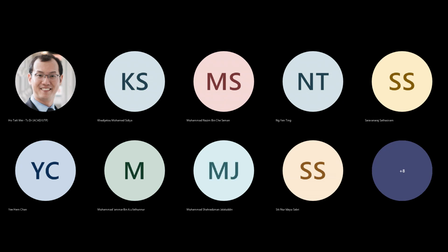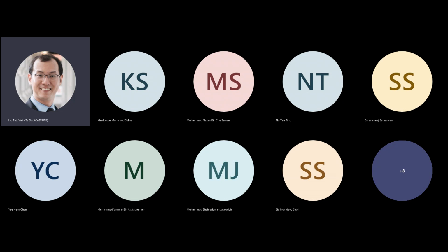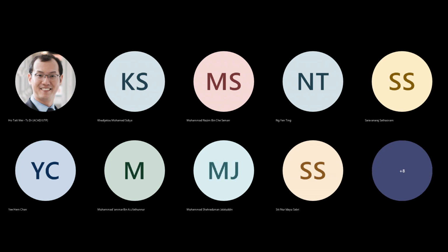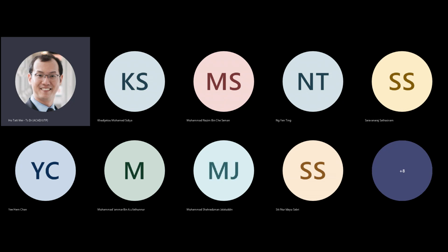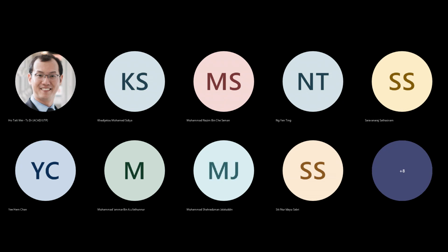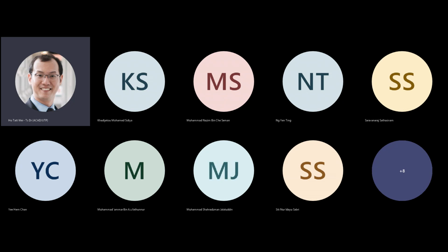And of course we've seen just now that the NAND gate basically looks like this in CMOS. So this is the first stage output. This input here corresponds to maybe this terminal here. This input here corresponds to this terminal here. This is an output. This output goes into the input terminal of a second stage NAND gate like this. Okay, so we're building this up from basic building blocks.